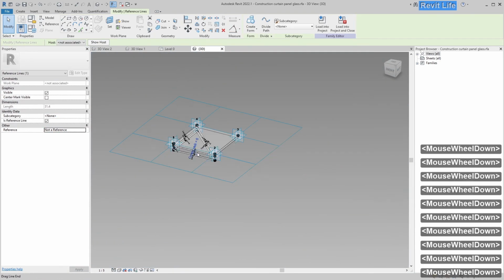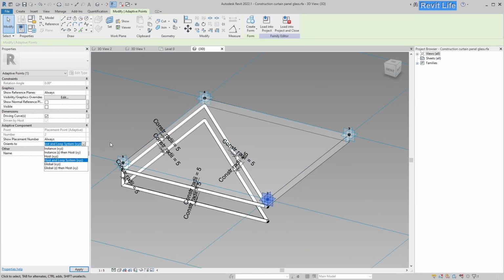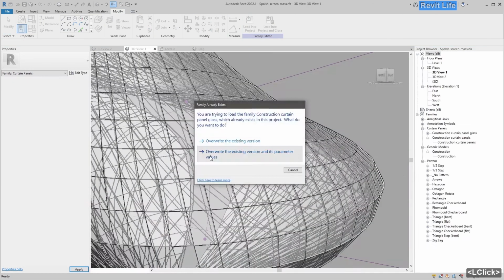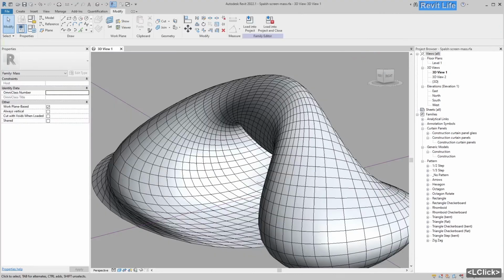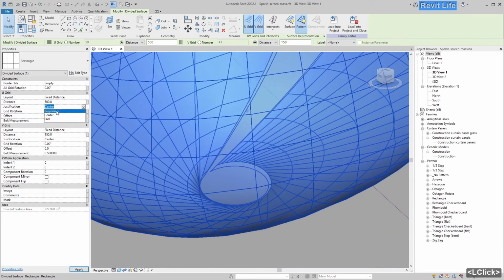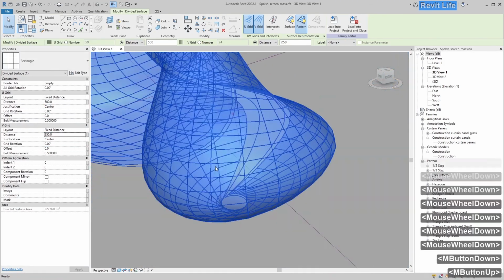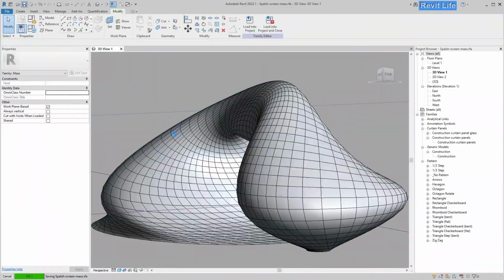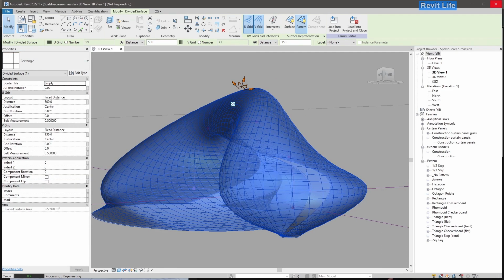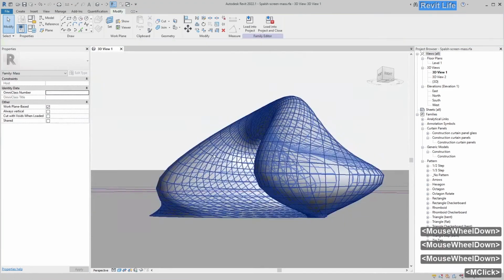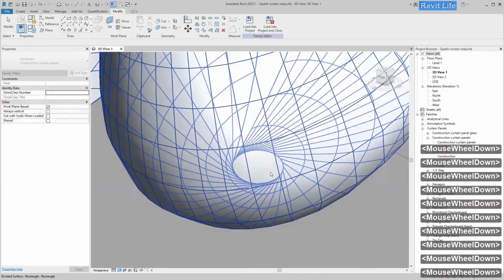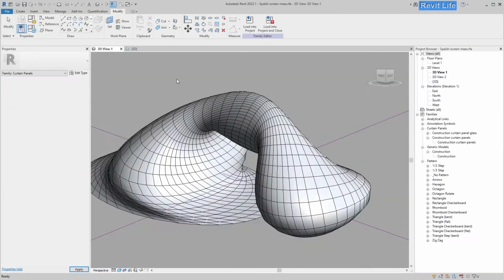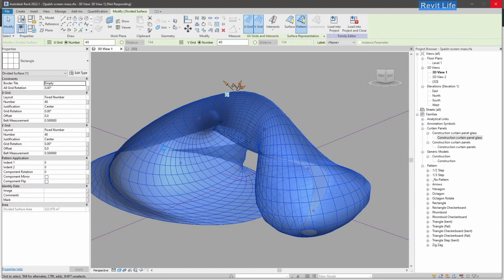And then I reread the help for pattern components, and there in the best practices there's a sentence that says, using sketched lines, create extrusions and forms to give the component dimension. Another tip is to switch border tile to empty or to full, not partial, and that way it speeds up the calculation and the population of the divided surface. And now I'm remaking the surface again and trying to get the closest shape to the splash image.